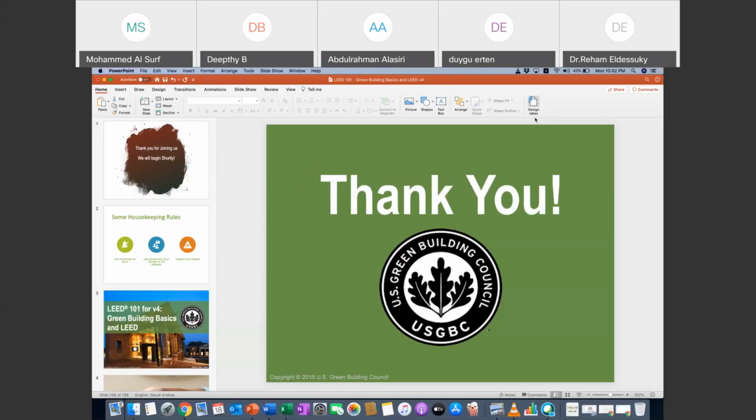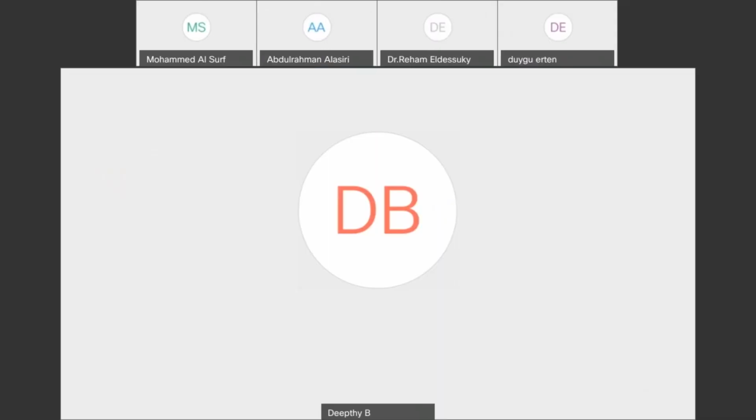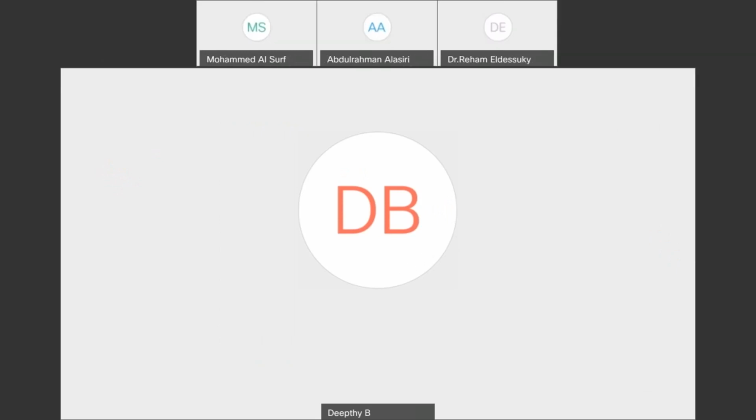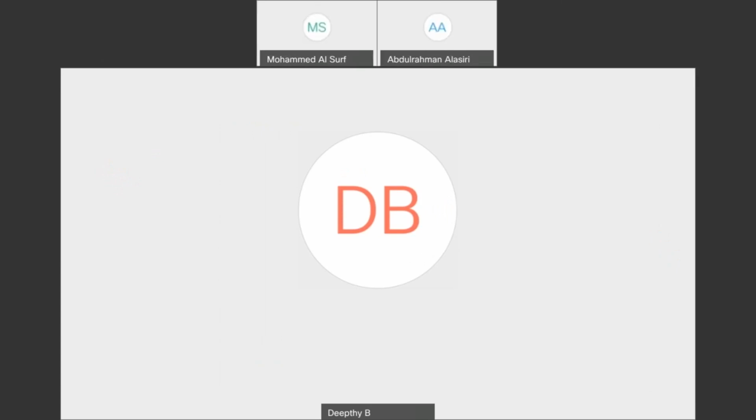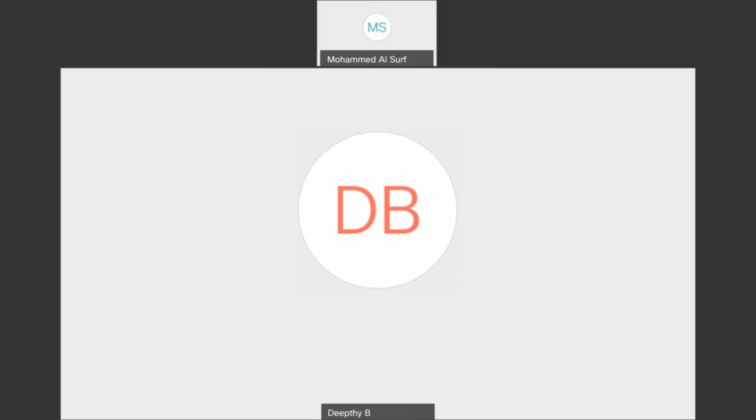Hi, there's a question on IEQ: why have occupant behavior and adaptive actions not been included in the content? I'll take that question. While we deep dive into the IEQ credit categories tomorrow, occupant behavior and these actions are extensively upgraded in our LEED version 4.1 O&M rating system, where there's a category on occupant comfort and satisfaction. While it's not just a survey, we also monitor carbon dioxide concentrations and TVOC content across the building, and also evaluate all regular building occupants for their comfort. We'll go into that in more detail when we focus on the 4.1 O&M session.